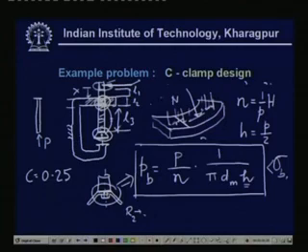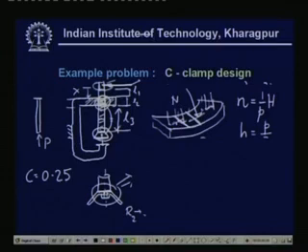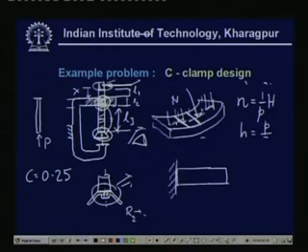There are other kinds of stress in the thread. So, if you consider a little part which is, let us say, unit distance apart, and look from this side, then what you see looks like a cantilever beam, because this side is firmly grounded.